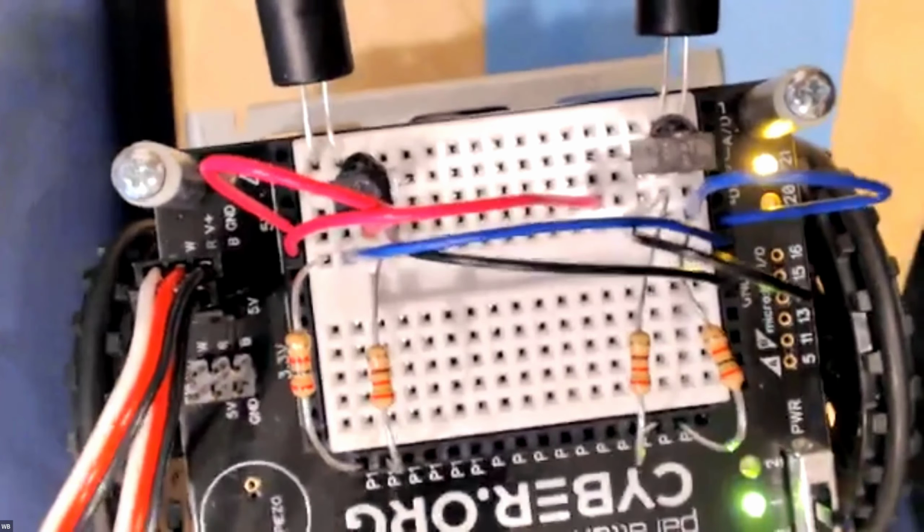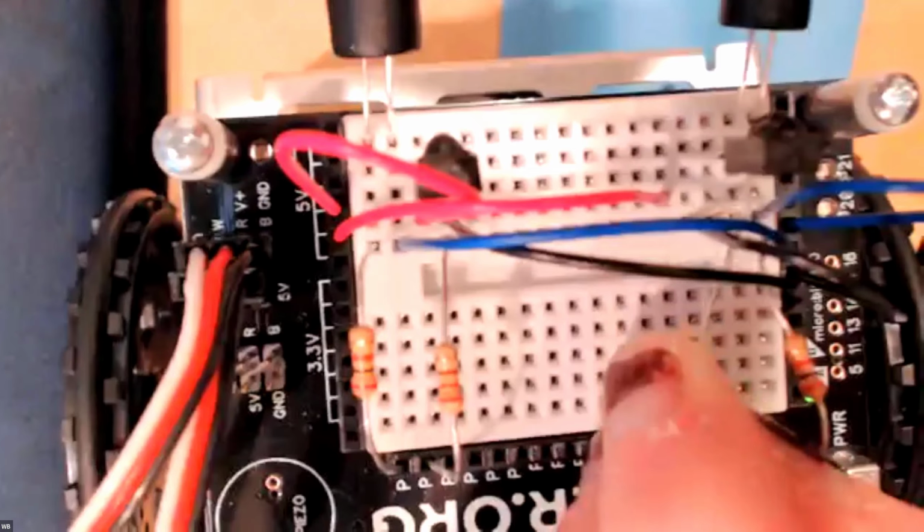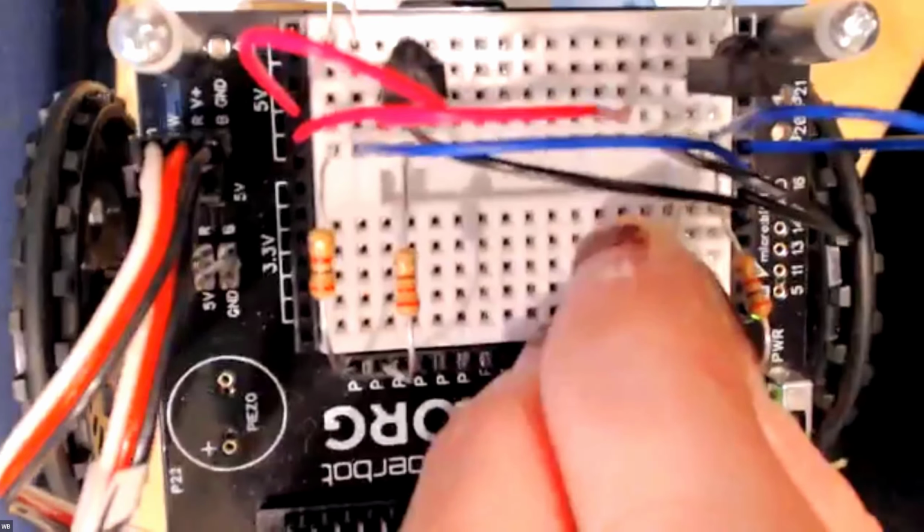Okay, so I see a resistor that looks like it might be going into, this may be the angle, but check your 220 ohm resistor. How many rows up is that going? 220 is which color? Red, red, brown. Is it going to the 4th row up? Red, red, brown is going to the 3rd row up because the black wire is in the 4th. Okay, I have those.